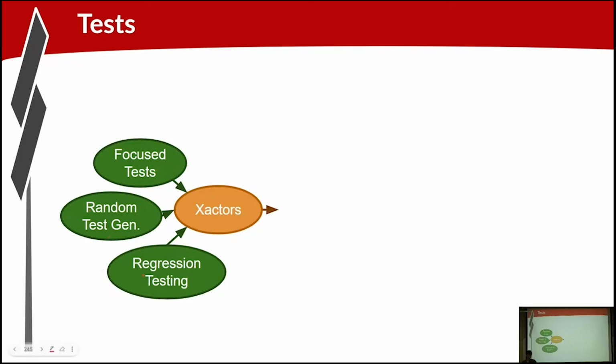To a greater degree, we also have regression testing, right? And this is our way of making sure we don't go backwards. So as much as possible, as you're developing tests, you try to enable those tests as regression tests, meaning every time you make a change to the model, the regression tests will be run against that change and make sure they're still passing. So it's our way of making sure that we don't step backward. Anything that's in the regression test is a gating function for changes getting into the model, so they prevent bugs from getting into the design.